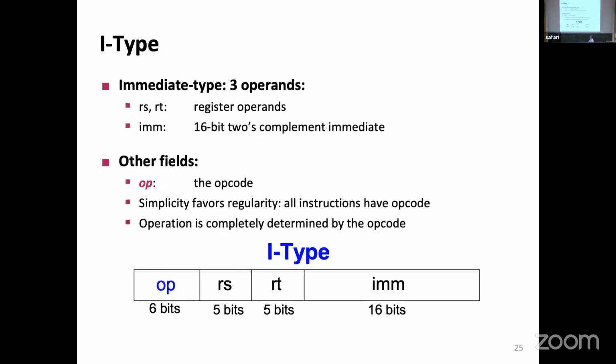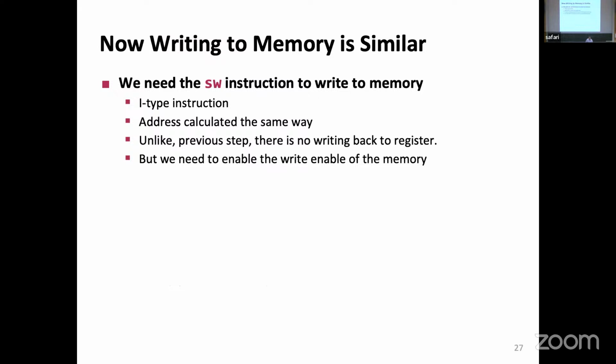And so we have a different type of instruction. I need two registers. One of them showing me the base address where the memory will be. One of them, the register that will be read into. Then I have the constant here. So this constant, I have 16 bits to encode it. I'll probably manage to write 24 in those 16 bits.